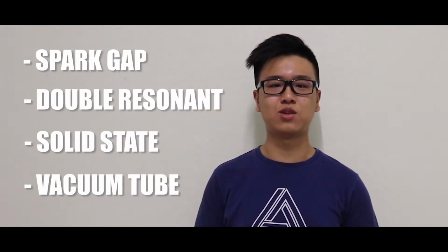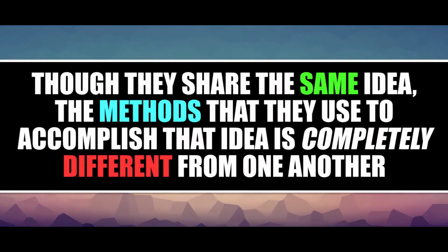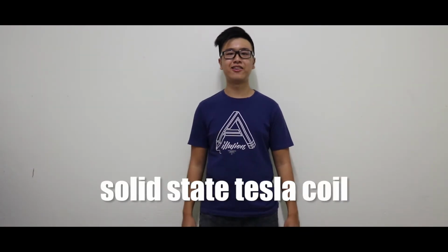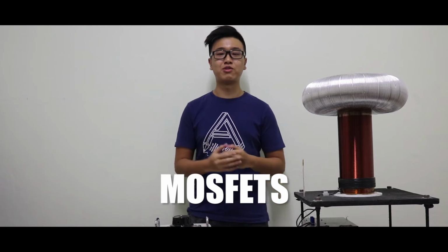There are many types of Tesla coils, those being the spark gap, double resonant, solid state, and vacuum tube. Though they share the same idea, the methods that they use to accomplish the idea are completely different from one another. For today, we'll be looking at the solid state Tesla coil, otherwise known as an SSTC. The solid-state Tesla coil replaces the conventional spark gap with a half or full bridge MOSFET, a type of transistor.